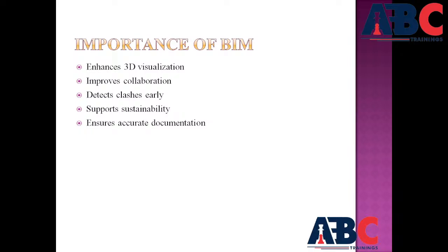Accurate documentation and cost estimation. Because BIM elements are data driven, all construction drawings, schedules, and quantity takeoffs can be generated directly from the model. This ensures precision and consistency. One change in the model updates every related document automatically. This leads to more reliable cost estimation, fewer manual errors, and efficient project delivery.